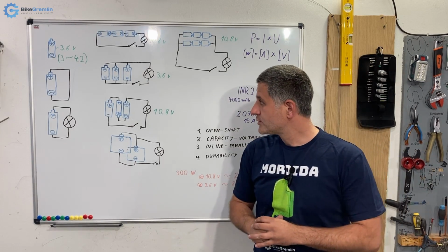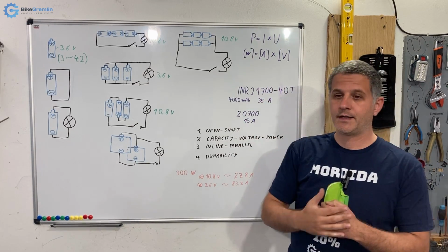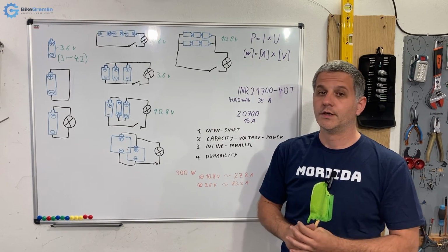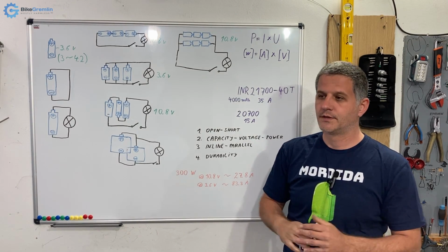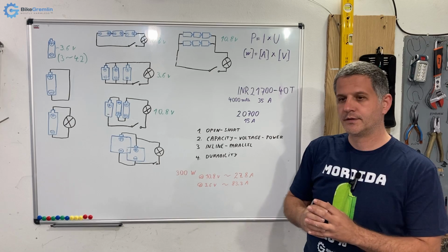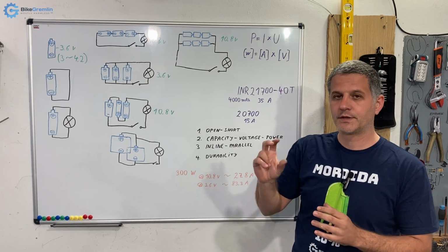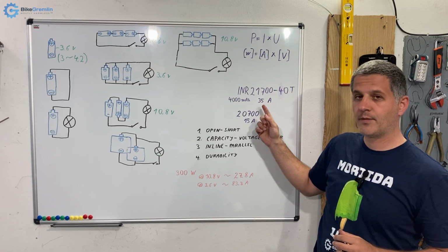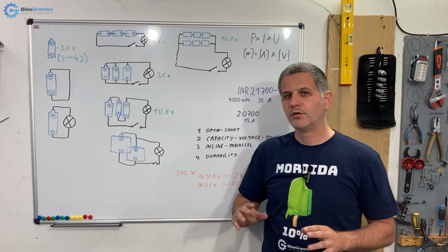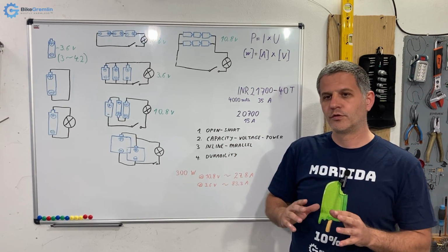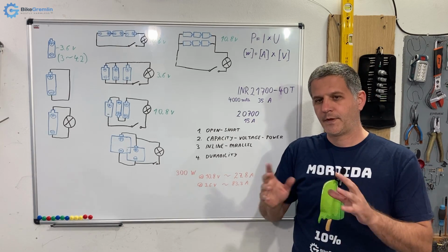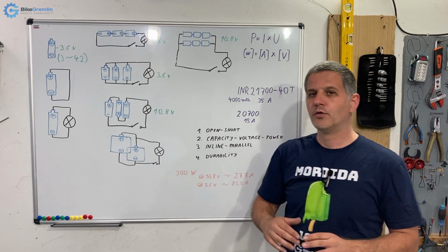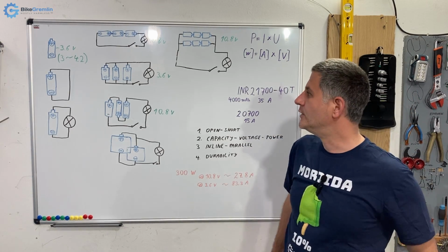Now it also has a maximum current that it can provide. So if you want to use a higher power, you can use more current, but it will not last as long. This one allows you to take 35 amperes for a longer period, or about 45 if you control it for heat. And that's a bit more nuanced. I won't be going into that, not in this video.